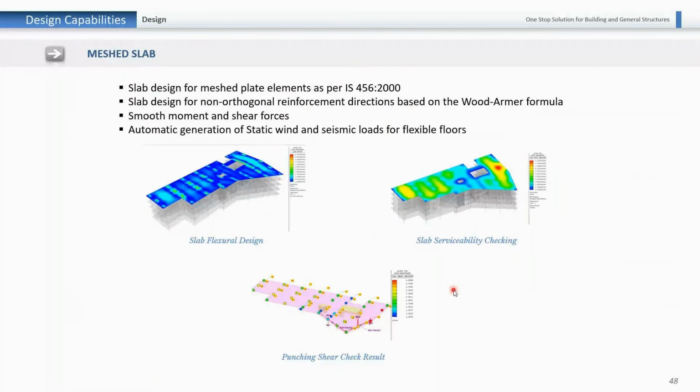Also, we can do slab design inside the software, which will be FEM based design, in which Wood-Armer moment can also be calculated. If you see, flexural check, serviceability check, and punching shear checks can be done. Similarly, mat foundation design can also be done over here itself.